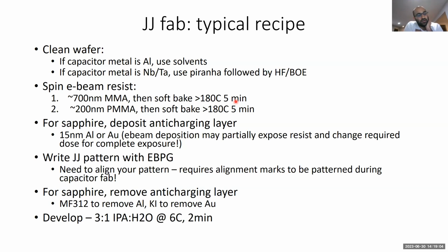Yeah, great question. So we don't rigorously follow expiration dates. Basically, we buy a big bottle, like a quart of resist, and we store that. Then for the specific resist that we use, we pour it into smaller bottles, and we take resist from those bottles and dispense it onto our wafer. That's done to minimize the number of times you open your main stock bottle.